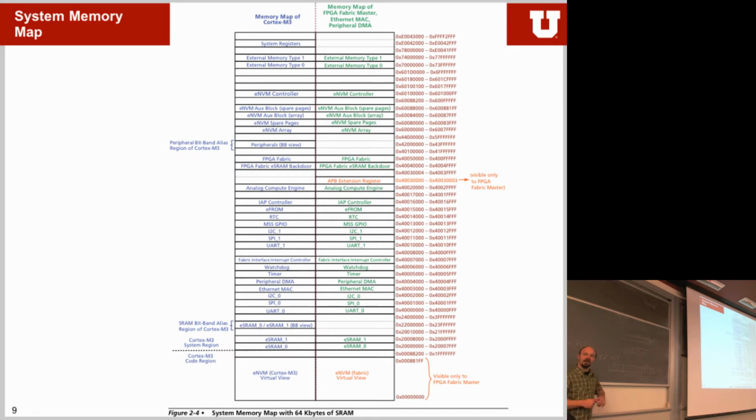Right? So now, oftentimes they have a trick. What they do is instead of just one of these registers, they have 3 of them. One of them will be the status, one of them will be the set, the other one will be the clear register. So they are all 32-bit wide.